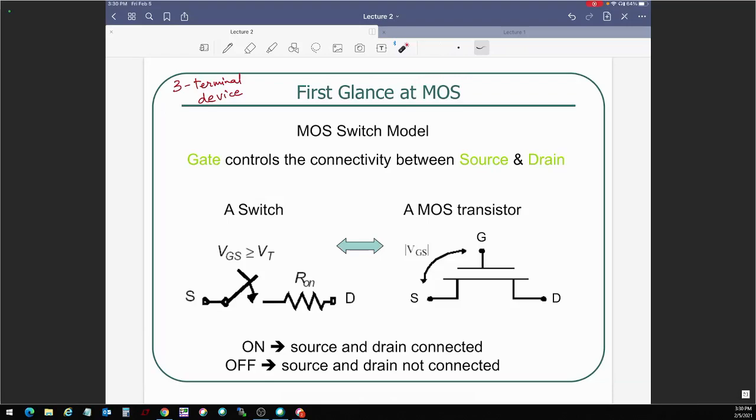So what are the three terminals for a transistor? Well, it depends on the transistor, right? If it was a BJT, the bipolar junction transistor, then the three terminals would have been emitter, base, and collector. Something that emits electrons, something that is able to control whether electrons are able to make it to the collector or not, and then the collector is sort of where all the charge is collected, right? Three terminals. The base is what controls the state of that BJT transistor acting as a switch. That's the story for BJT.